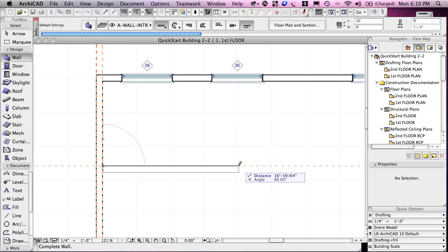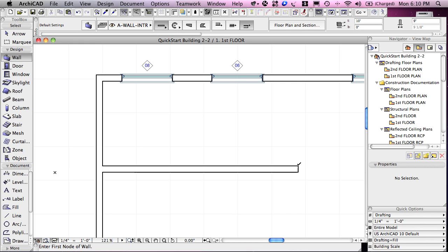And now you can see that the preview of the wall is correctly placed down below the heavy line, which is the reference line. Now I can do this a very specific distance, or I can just gesture, and in this case, just sketch out that this room might be wide enough to have these 2 windows included.